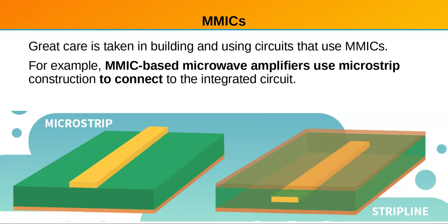In microstrip, it's just copper on the PC substrate that is designed to create a 50 ohm transmission line. Since you know the dielectric and the spacing, and the thickness of the conductor and the width of the conductor, those are all factors to calculate how to make that a 50 ohm line.